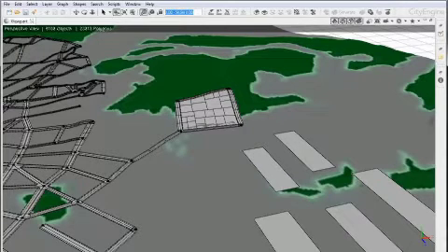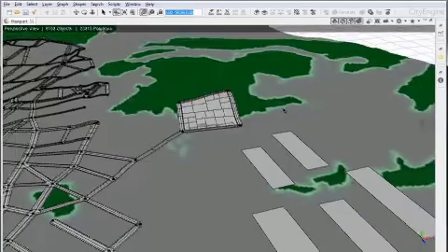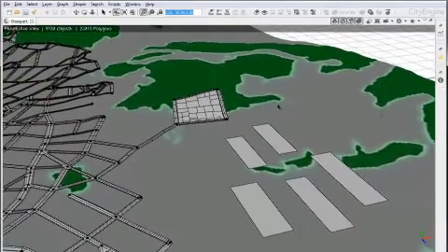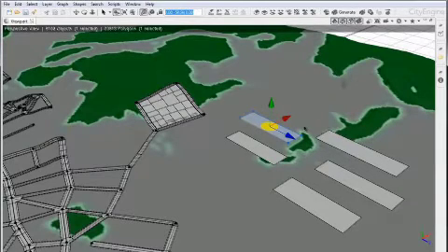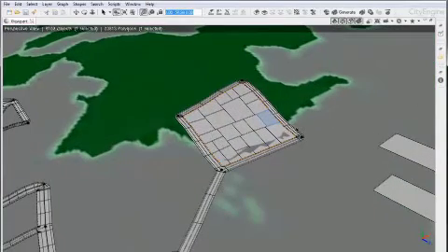In this fourth part of the tutorial, we are talking about aligning elements in the scene. So we are talking about aligning graph segments and shapes and the terrain itself. One of the first things I wanted to quickly mention is that there is a difference between so-called static shapes, which were either imported or drawn manually with these tools up here, and the so-called dynamic shapes, which are produced by CityEngine's dynamic city layouts system.